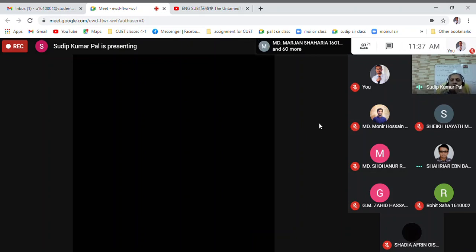এবং ওইটা মেনটেন করা খুব ডিফিকাল্ট, ওই জায়গায় এটা হতে পারে। বাট আমি যদি আরবান স্লাম এরিয়াতে করি যেখানে গ্রাউন্ড ওয়াটার হাই, পপুলেশন ডেন্সিটি ভেরি ভেরি হাই, চেঞ্জেস আর ভেরি র্যাপিড, আজকে এখানে আছে কালকে ওইখানে থাকবে না, তাহলে সেই ক্ষেত্রে কমনলি টিপিক্যালি পিট ল্যাট্রিনস লাইফ, ডিজাইন লাইফ ইজ 1 to 5 years. Exceptionally is too long if the conditions exist.